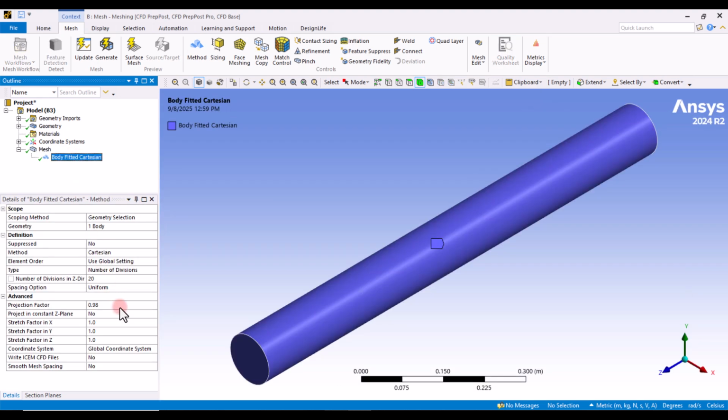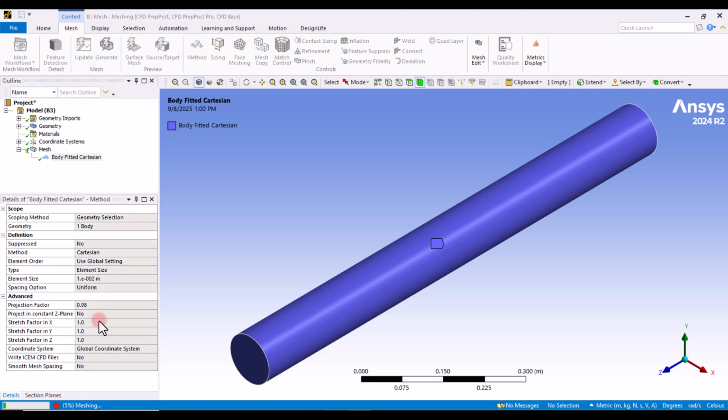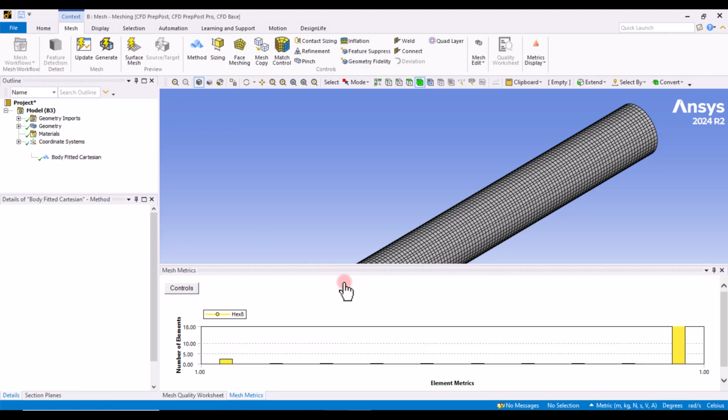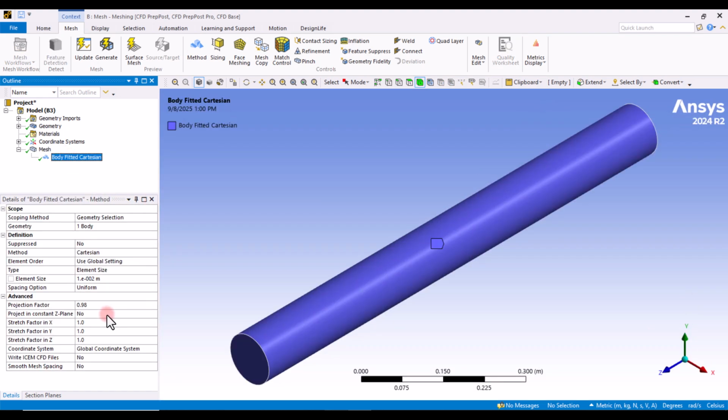So let's see what has changed in here. First of all, we forgot to turn back the element size to detect smaller elements. And right now, I guess we can have the full curve and cover the full pipe. So right now, you can see it just did the opposite and tried to put all the initial cells on the surface of our pipe. So for additive manufacturing, the default is 0, which is what we need for this type of simulation.